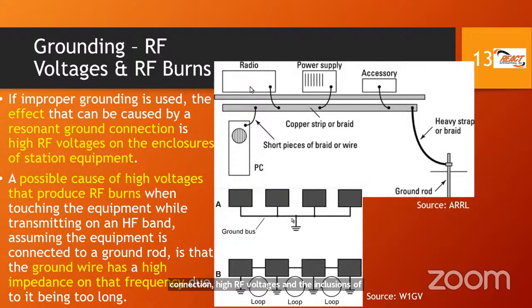So on the equipment, you could actually touch the equipment and you can get, quote unquote, a shock, right? Or the other bullet point is that you may get a burn, or what we call an RF burn, and that's not nice, that's quite nasty. So grounding and bonding will assist in removing that issue or reducing it significantly to the point where you are safer than if you did not, right? So grounding is important.